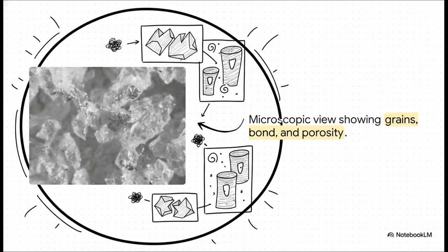First, you have the sharp abrasive grains themselves. Second, the bonding material, acting like tiny supporting posts holding those grains in place. And third, and this is wildly important, empty space. We call this crucial empty space porosity. If you don't have enough empty space in the wheel, the tiny shavings of metal have literally nowhere to go, they clog up the wheel, and the whole cutting process just grinds to a devastating halt.